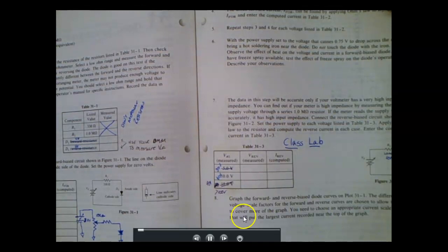I'm going to hook them up in series aiding. Series aiding means, y'all actually did that in DC too, that your voltages are added together. We can do that with batteries, guys, or with any power supply. I'll show y'all that. I take the negative out and hook it up to the positive, negative, positive, negative, positive. I've got 4 power supplies, and we can get about 30 volts out of each one of those. So that means I can get 140 volts out of these stacked up together.